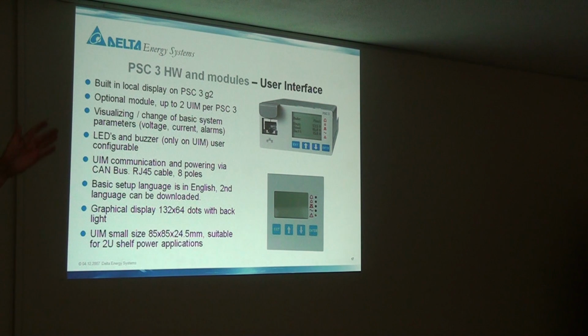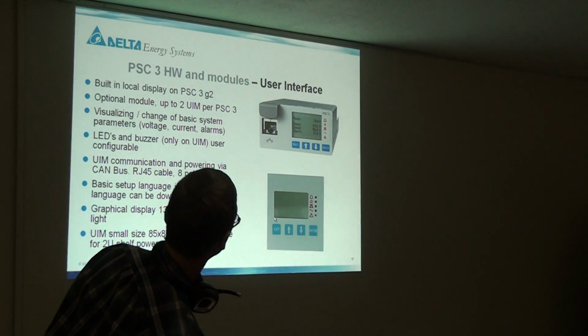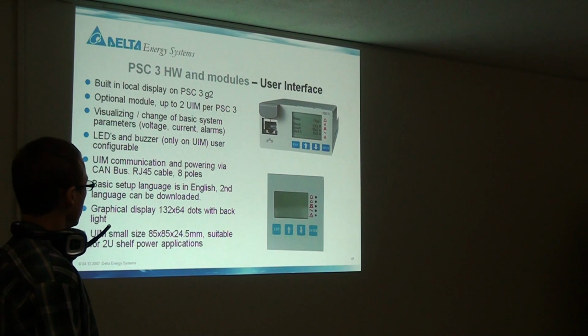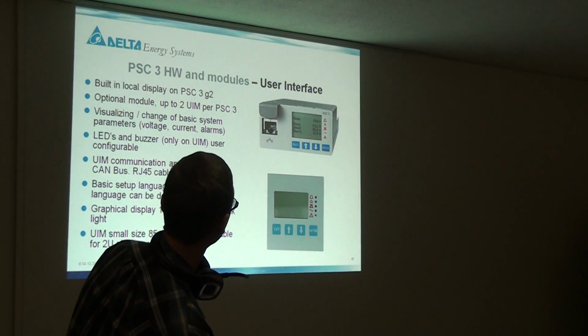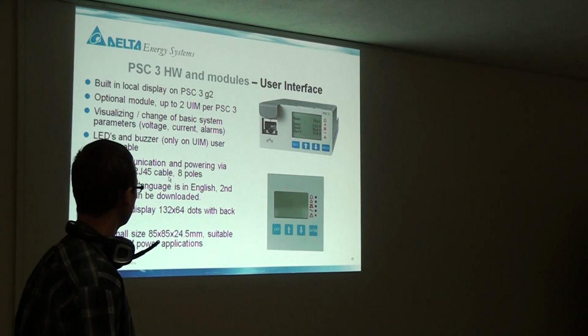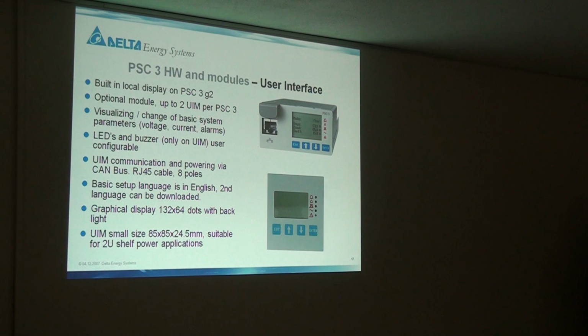LEDs, we have the alarm LEDs or status LEDs. We have a buzzer on the UIM, which you can enable or disable. It's user configurable. We have UIM communication and powering via CAN bus, also an RJ45 3-pole cable. Then we have a basic setup. The language on all the systems is English.